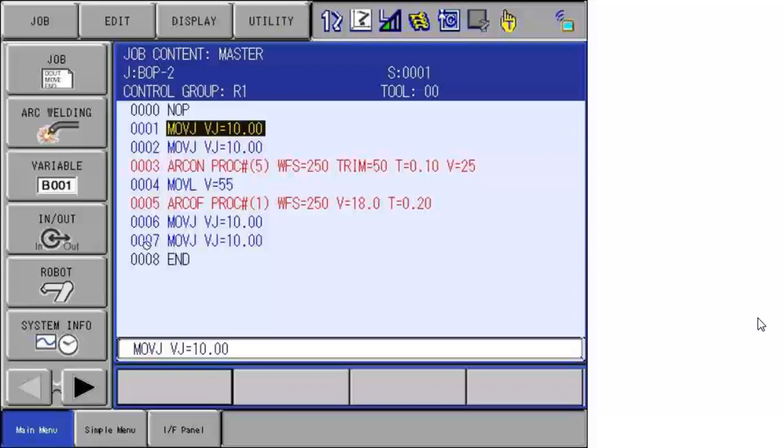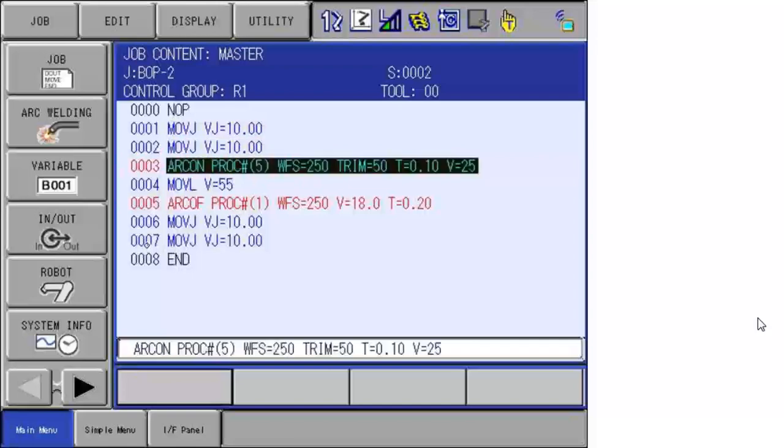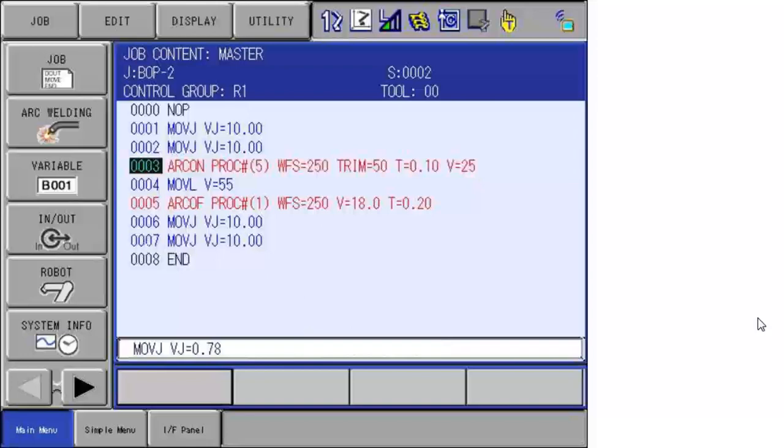Inline tags, when you save jobs or load jobs, the settings will be in this instruction. You can use different settings for different weld locations on a part. However, if you change it in one place, it won't change it in others, and it's unique. For the global parameters, most people use arc start files because you can use the same file in multiple locations that might have that joint type. Again, it's a preference.